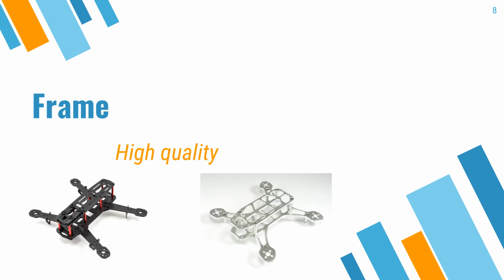The frame is basically the skeleton of the drone, because it keeps everything together and all the parts are assembled on it. Let's look at some examples here. Below we see 2 high quality frames, the left one made of carbon fiber and the right one of aluminium. Both are strong and very suitable as a drone frame. However, carbon fiber is lighter, has a sufficiently higher stiffness, and is also more rigid than aluminium. So carbon fiber is way more often used than aluminium.